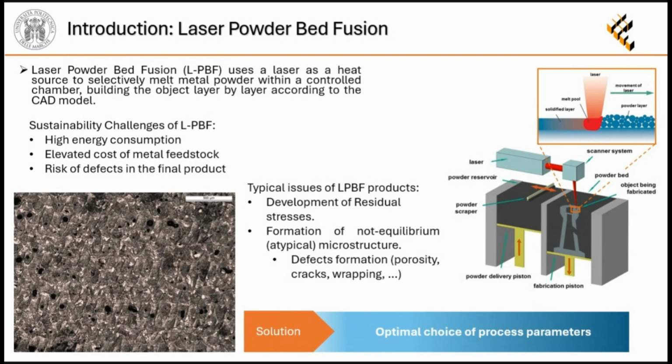In fact, it's important to find a way to reduce the waste, and in this way it will be possible to increase the sustainability of the technology. The typical issues of LPBF products are the development of residual stresses and the formation of non-equilibrium microstructure with a lot of defects like porosity, cracks, warping, and so on. So the solution is to find the optimal choice of parameters.